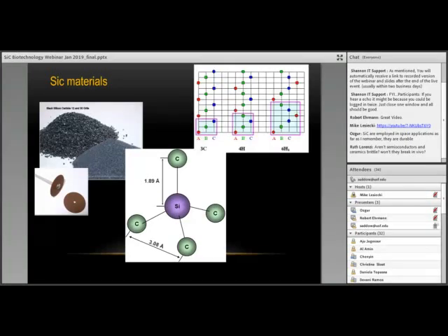What's interesting about silicon carbide compared to diamond and silicon is that it forms in single crystalline form in more than 200 different crystal orientations. These have actually quite an interesting technological ramification. The 4H material is a hexagonal polytype, as we call it, used in power electronics. 6H is a great support for LED lighting, used by Cree and other companies. And the cubic form can be grown on silicon wafers, which we'll get into in a moment.